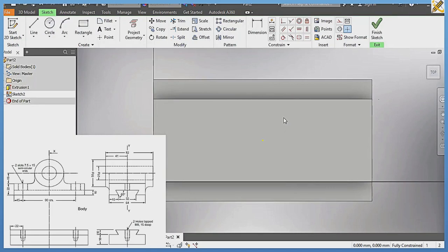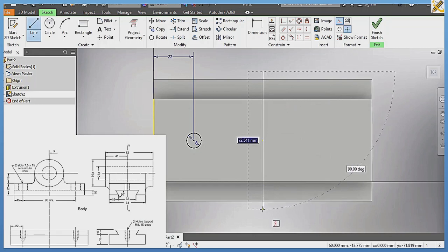We are told that we have two holes of diameter 8 and depth of 15. The first one is going to be right. Let me locate, that's the midpoint right there, diameter 8. Mark of 22. All right, so pick symbol for hidden line, then pick a line, locate this midpoint. I'm producing that line right there.